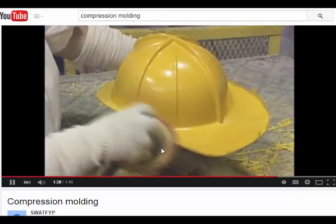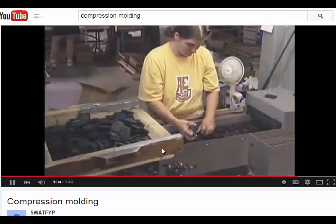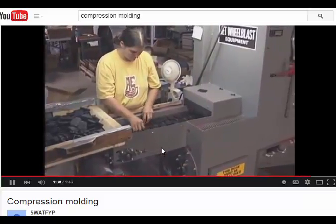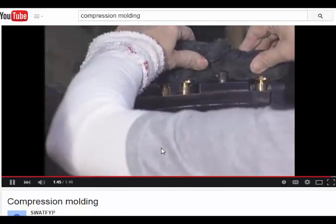After demolding, any flash is removed. This is done either manually or through the use of deflashing processes such as abrasive blasting. Several factors influence the molding conditions during compression molding.